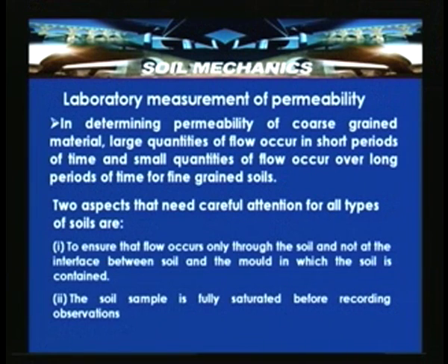Before looking into the laboratory measurement of the permeability, two important aspects have to be understood and ensured. In this slide, in determining the permeability of coarse grained material, large quantities of flow occur in short periods of time because of the large pore spaces.